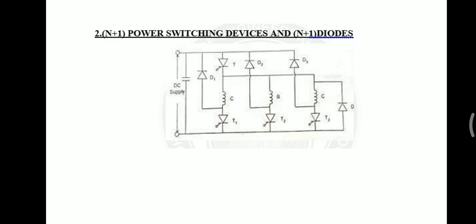So here the merits are that the converter uses a smaller number of switching devices, with freewheeling during the chopping period. The voltage rating of the overall switching devices is very low. And the demerits are that the ability to demagnetize a phase winding is very complex. At higher speeds, the outgoing phase cannot be de-energized.